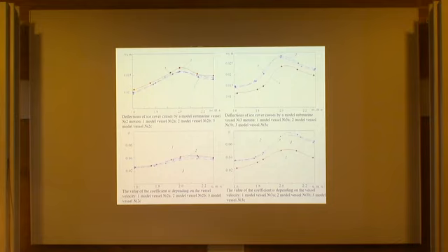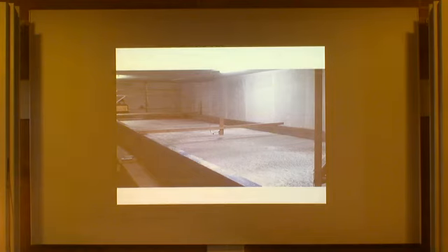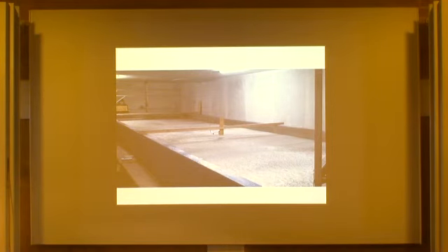The protruding parts do not significantly affect the parameters of generated flexural gravity waves, but the form of cross sections can influence the curvature of flexural gravity waves. We will note that for submarine vessels of other models in operation, such kinds of experiments are also necessary. Character of the failure of the ice cover by flexural gravity waves during the motion of model submarine vessel number 3B at critical velocity.